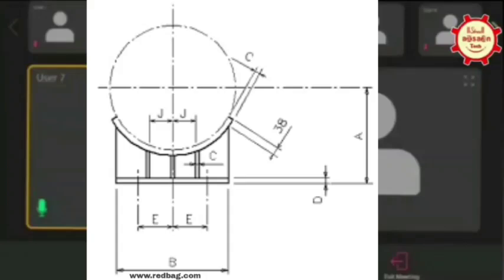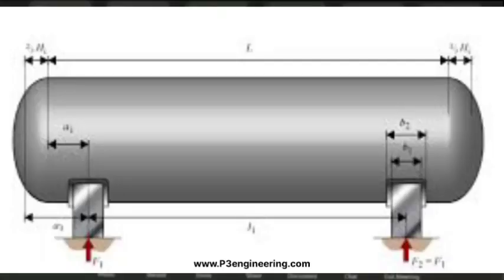That's why, in a similar case of a 40 to 50 meter vessel, considering a third saddle would result in a much more complex problem and equations, so solving it the way 2 saddles are designed would not be a correct method. So you are suggesting go for 2 saddles only, right? Yeah, 2 saddles or FEA.